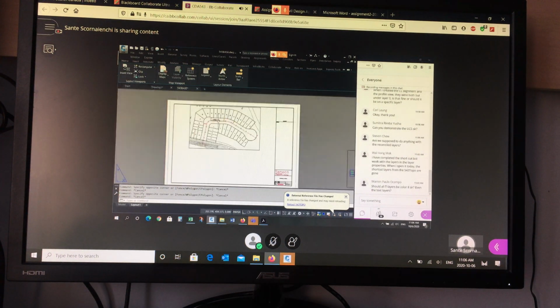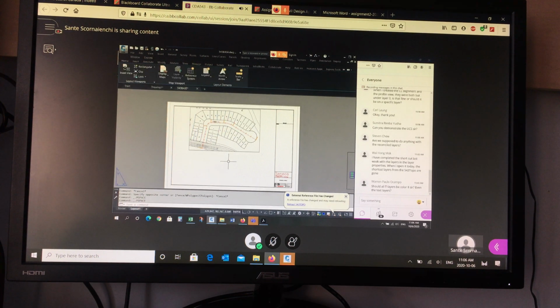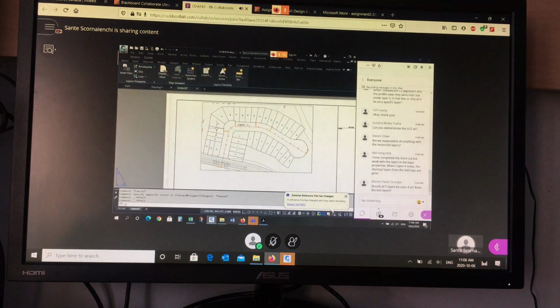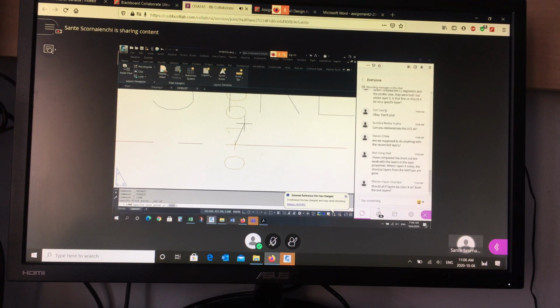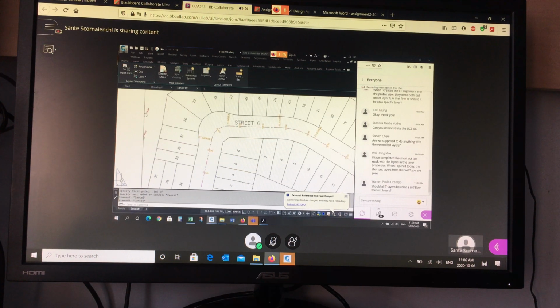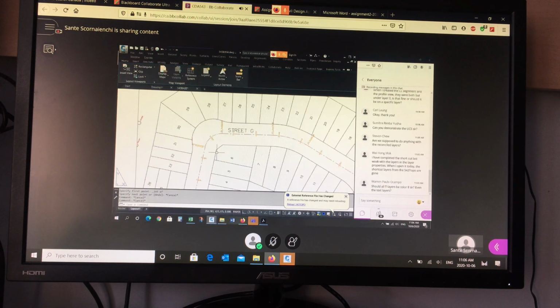And the way you do this, and it's all done in paper space, right? Notice I'm not inside any of the views, I'm in paper space. I'm going to draw a vertical line at any station in the horizontal part of the view, right? So at 100 or 120. Then I snap to exactly here with an intersection. So even though I'm in paper space, I can still snap to stuff in model space, right?